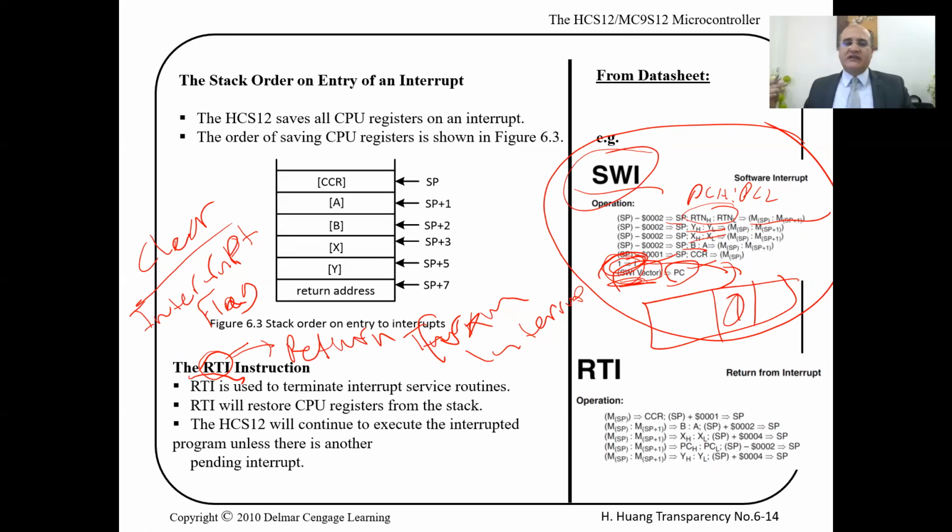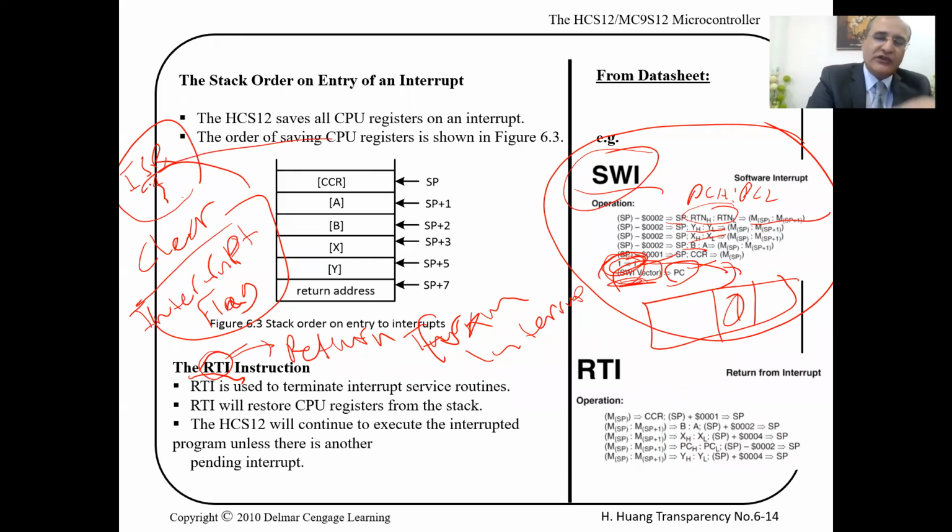The hardware will detect an interrupt flag raised. It will respond by sending the program counter back to the interrupt service routine, execute it again, then exit the interrupt, find that the flag is still high, and bring you back to the interrupt service routine. So the response is like the CPU is stuck. It doesn't respond, jumping between the interrupt service routine, leaving it, going immediately back. Okay, so after servicing the interrupt source, you have to clear the interrupt flag. We're going to see that.